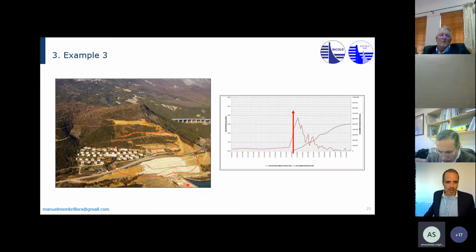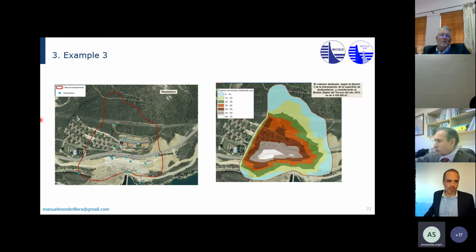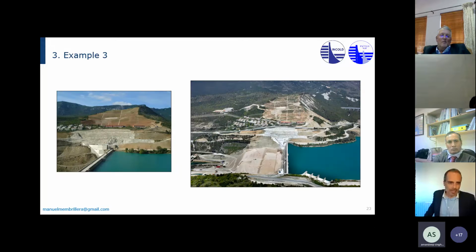This is the old dam crest, and this is the huge, massive landslide we had. All these people had to be evacuated. Inclinometers and piezometers were installed. All this earth was removed, removing weight from the top of the landslide and placing it somewhere else, then drain, get all these people out, demolish the buildings, and grout and hold this.